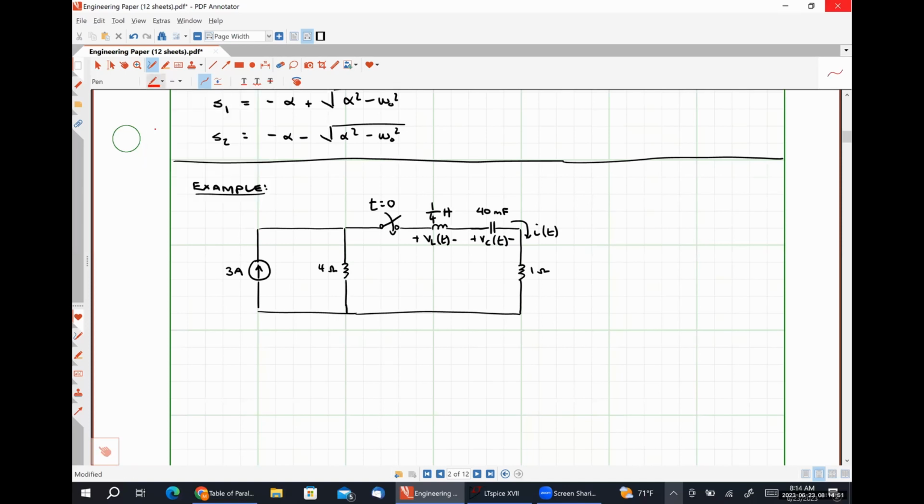And the quantity that we're interested in solving for this circuit will be the voltage drop across this resistor. And in order to solve for the voltage drop across this resistor, the easiest possible thing for us to do would be to say that it's going to be 1 ohm times this quantity I of t. So we're actually going to wind up solving for I of t and then using I of t to solve for VR of t.